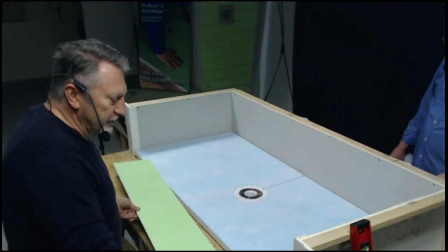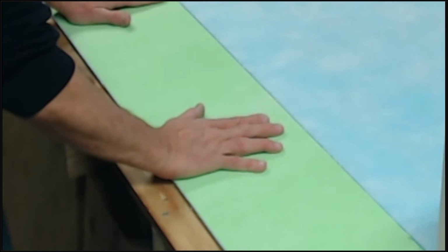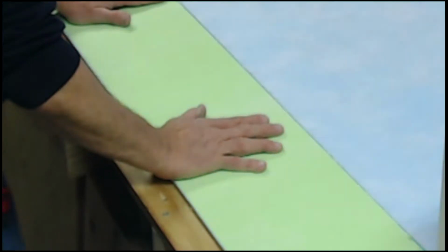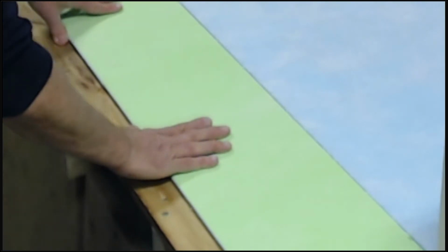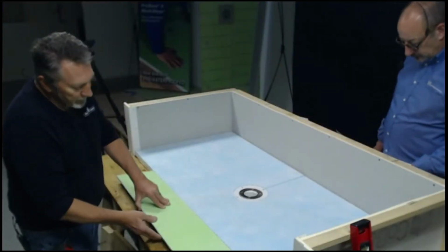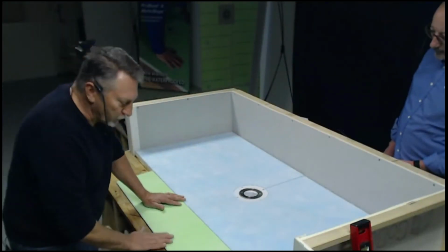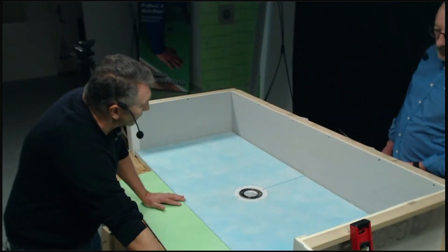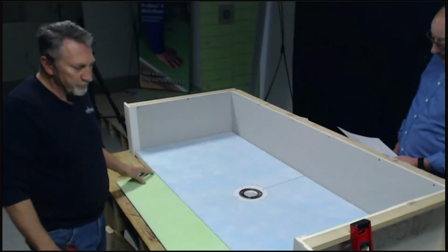So cut that down to the size that I need, and then just set that in. Flush is perfect. So you basically cut off the fat. Cut off that. Yep. Perfect. Now I have a nice smooth transition. Okay. Now it's a 1/4 inch height out here at the dry space. You're going to have to treat your dry space and get that ready for tile anyway. So that's why that'll come out flush with that. Okay. Gotcha. That's one option for you. All right. Well, that looks easy, Dave.